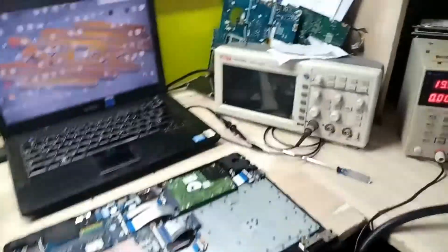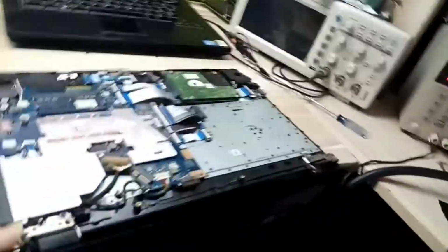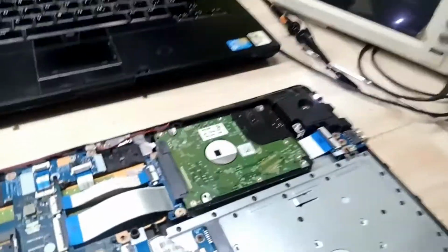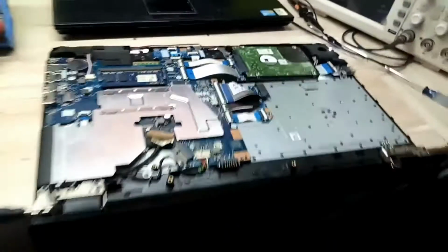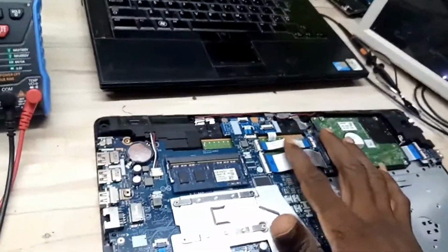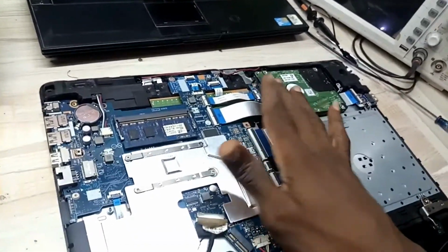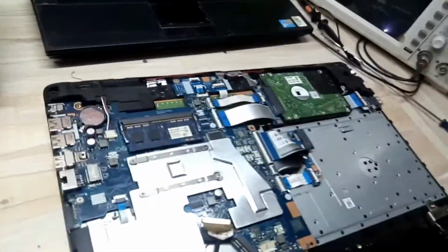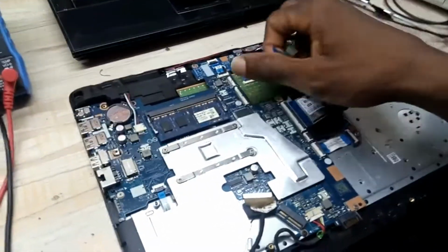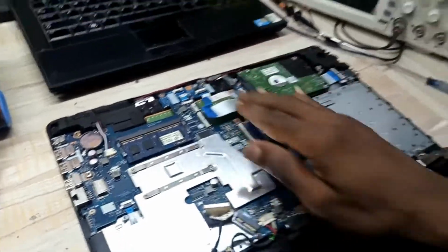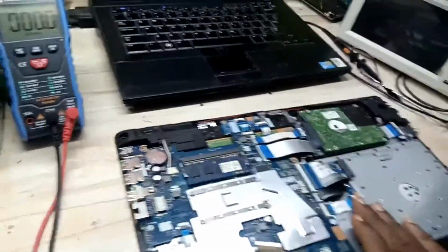So now I've opened the laptop and I'll power it again. I've powered the laptop and it has turned on. Still no display, and my board is still caps locking with this consumption. So what I'll do next is turn off the board and disconnect the hard drive, because I don't want a situation whereby the hard drive will be damaged. 100%, since I've removed the hard drive, the consumption will be different.